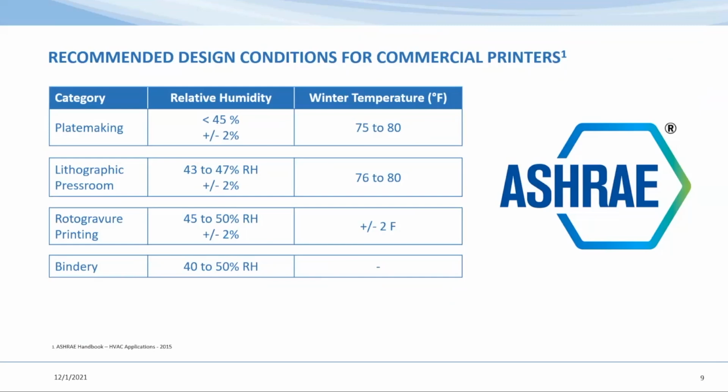The one thing I want to talk about specifically is not necessarily the set point, but how tight the tolerance is in these charts. When we get into products, understanding what product might be a good fit for your specific application is very important. How well can you maintain that space? There are many competing factors, like opening shipping doors, windows, or fans. Humidity is just one part of that, but how can we properly maintain it?